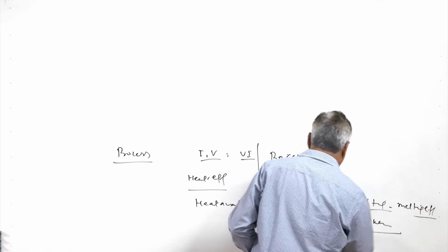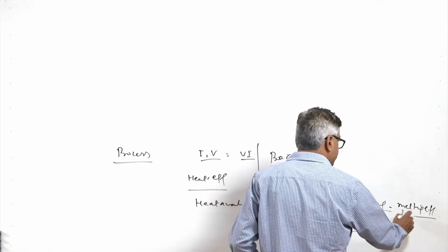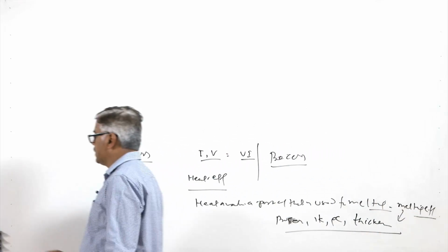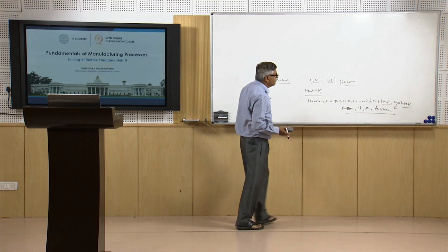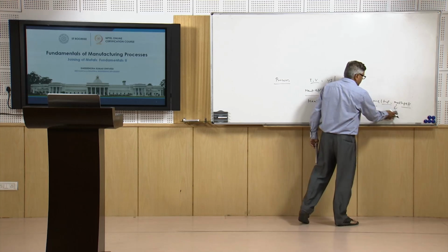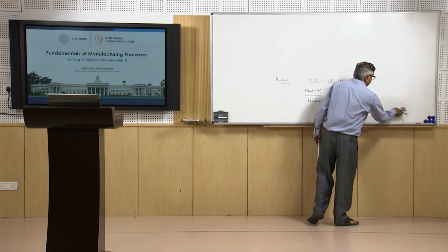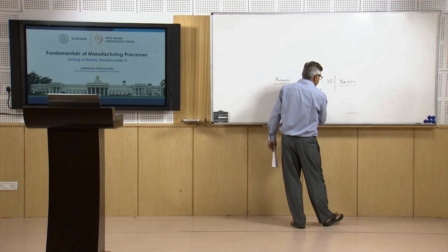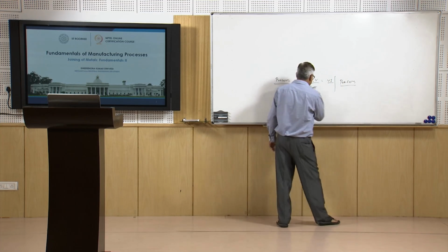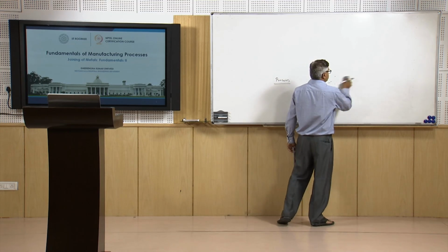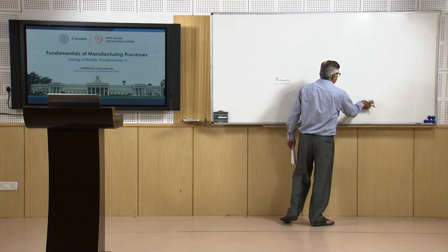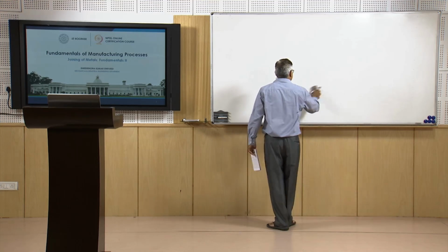All these factors affect the melting efficiency, meaning the proportion of the heat actually used for melting so that the joint can be obtained, while what proportion of the energy is converted into heat gives us the heat efficiency or thermal efficiency of the process.